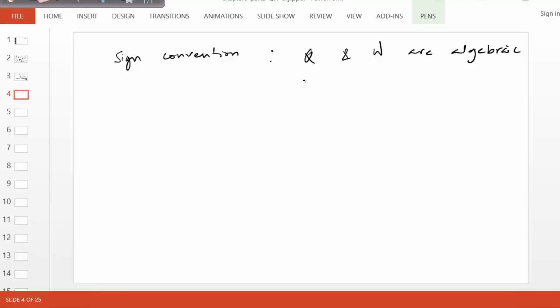And in an equation, you cannot say Q is going in, W is coming out. You have to use a sign, plus or minus, so that you know what to add, what to subtract. And by sign convention, which has been well established, we cannot get out of that, to memorize, we use something called Win-Hip. What does it mean? Work in is negative, heat in is positive.